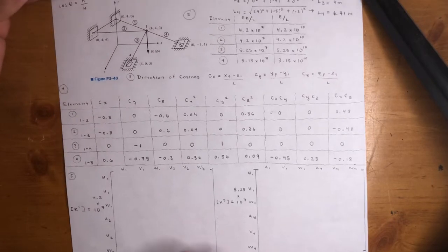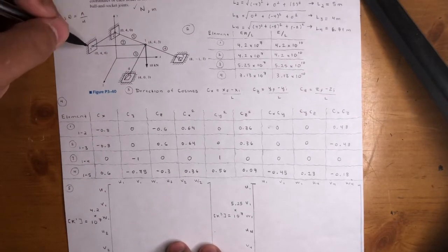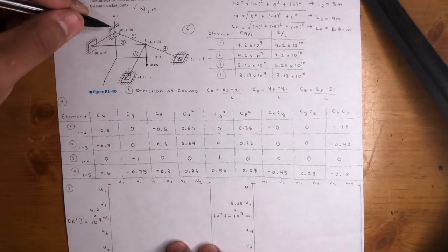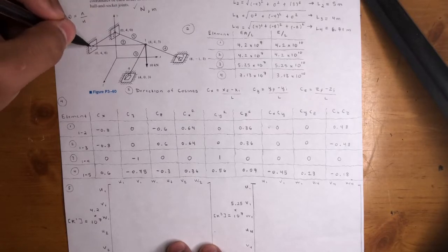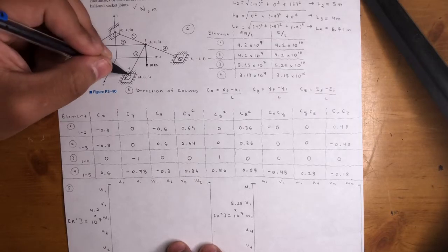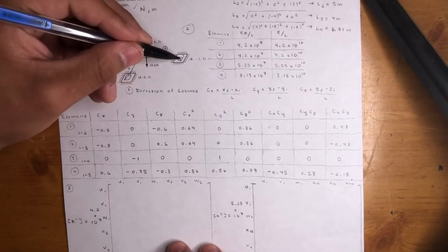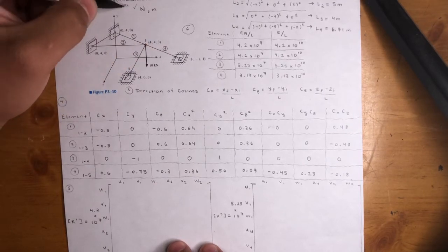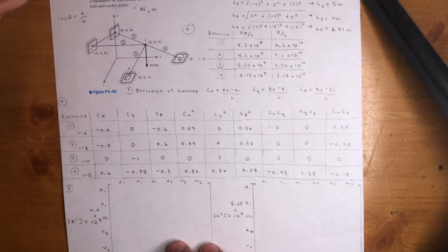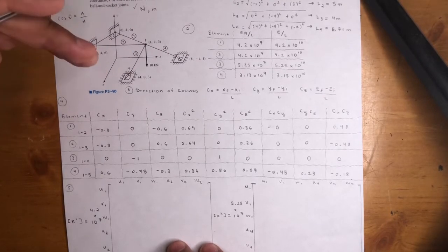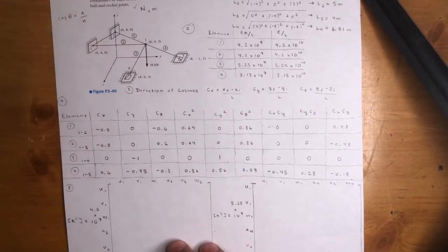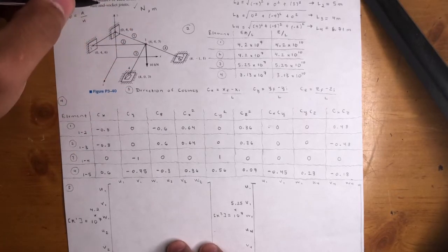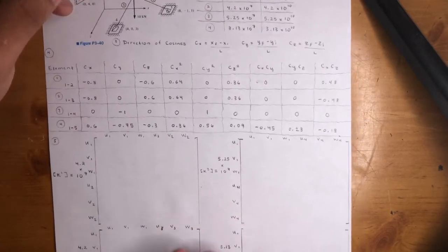So we know the boundary conditions: u2, v2, and w2 are equal to 0. u3, v3, and w3 are equal to 0. u4, v4, w4 are equal to 0, and u5, v5, w5 are equal to 0. Why did I say they're equal to 0? Because they're ball and socket joints. They prevent translation in the x, y, and z direction. They can only rotate, like a shoulder. Your shoulder can't go in the z, x, or y direction, but you could twist it. Same thing here. Since translation is fixed, they're 0.